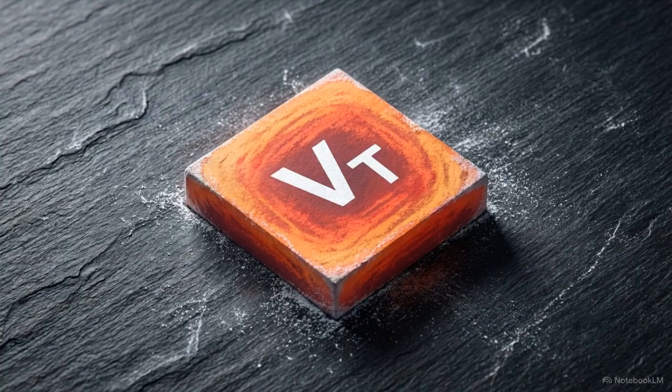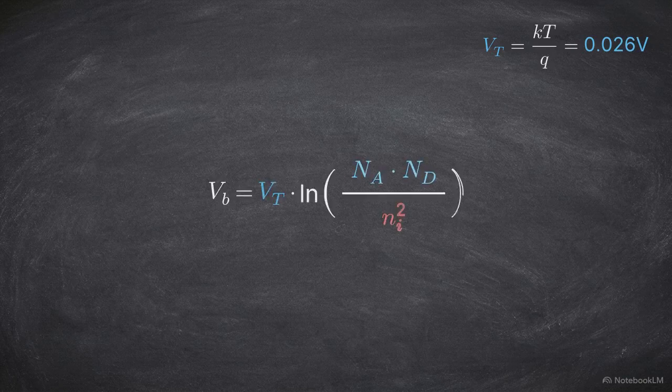The first step in finding the barrier potential is determining the baseline thermal voltage, or VT. At room temperature, Boltzmann's constant times the temperature divided by the electron charge rounds to 0.026 volts. We will use this constant as our thermal voltage throughout the calculation. The formula for barrier potential, VB, is the thermal voltage multiplied by the natural log of the acceptor and donor concentrations divided by the square of the intrinsic carrier concentration.